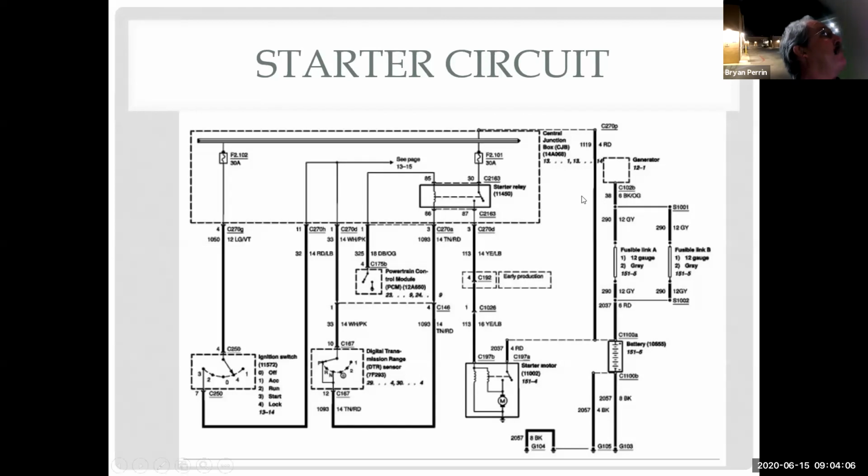Plus, could I apply power here at pin 87? And should it make the starter crank over? Yeah. If I put power here, that should energize this, cause this switch to close, and the motor should turn, right? Yeah. So again, I can test from here by supplying power. I can see if I got power and ground coming in. Relays are great places to test things at. It's one of my favorite places to test stuff at. They're easy to get to usually, and it allows me to split all 4 parts of the circuit to see where the problem is.